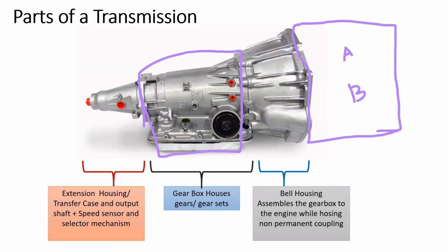So instead of doing that, you have the transmission in 3 pieces, the gearbox only in one section. The bell housing is a separate section, so you can swap the bell housing to match each type of engine. That reduces the manufacturing cost and complexity, and additionally it provides easy maintenance, because we can just remove from here and open the transmission or the gearbox from this side over here, right?